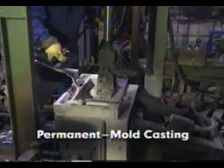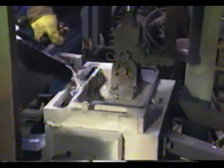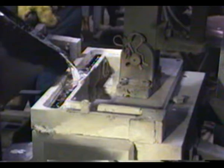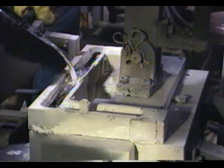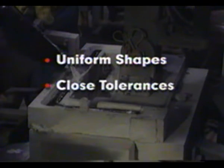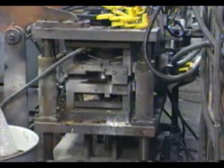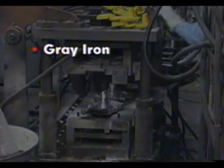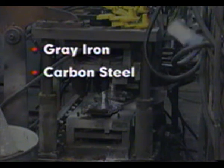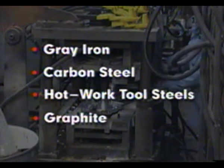Permanent mold casting is a semi-precision process, which because of the chilling effect of the molds, can provide superior mechanical properties. In addition, permanent mold casting can produce uniform shapes, close tolerances, and smooth finishes. Permanent molds are usually made of gray iron, carbon steel, hot work tool steels, or graphite.